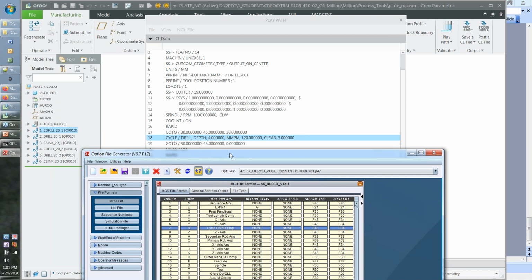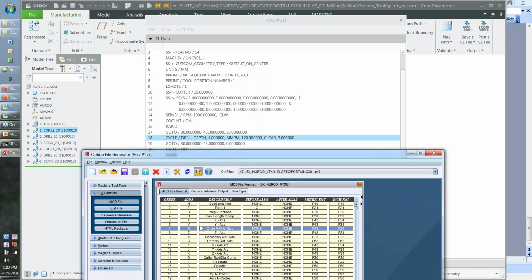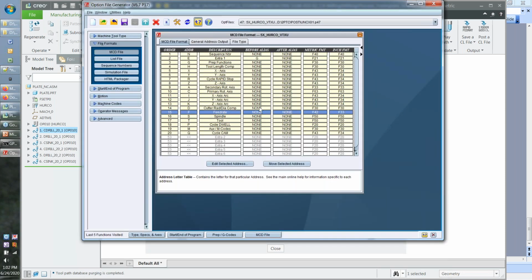It's going to make the same connection between the feed rate address, that would be the 120 that's shown here, and the F word that is shown in this table for feed rate, and subsequently the Z word for the Z-axis absolute position as it relates to the G81 line. So that's kind of how we get to the context of how GPost gets to outputting a G81 with a Z, an R, and an F on it. Okay, so those moving parts are all there.